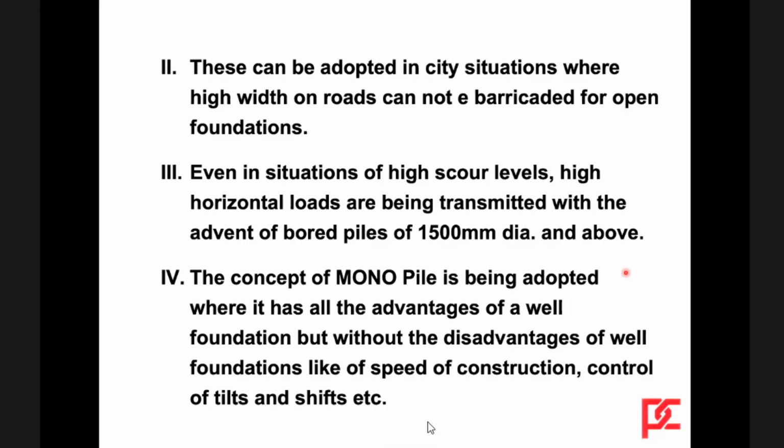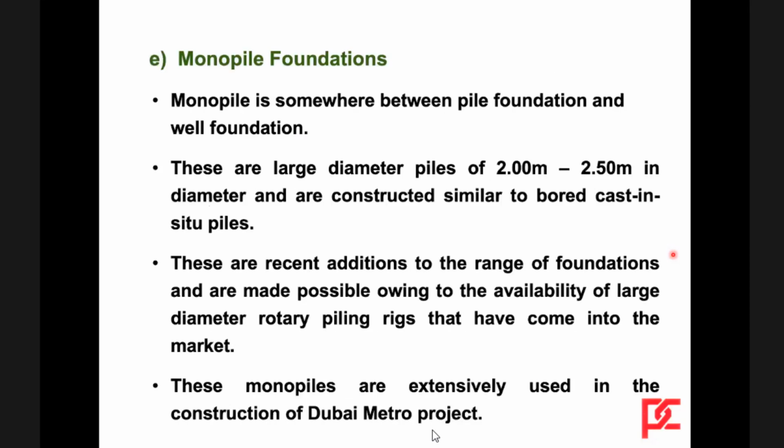Even in situations of high scour level, where earlier well foundations were being adopted, nowadays pile foundations are being adopted using bored piles of 1500 mm or even more. The concept of monopile is being adopted, where it has all the advantages of a well foundation, but without the disadvantages of well foundation like speed of construction, control of tilts and shifts.